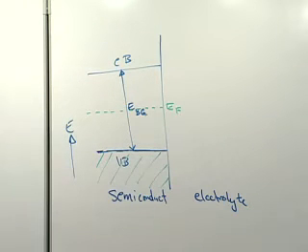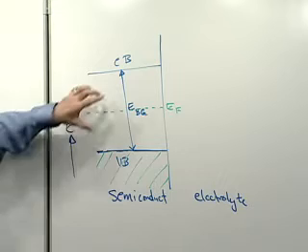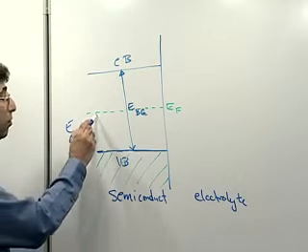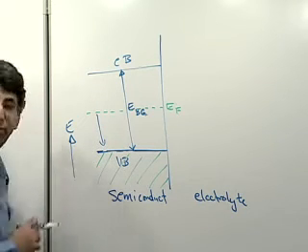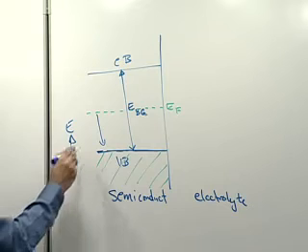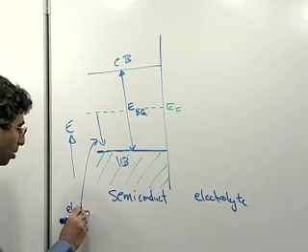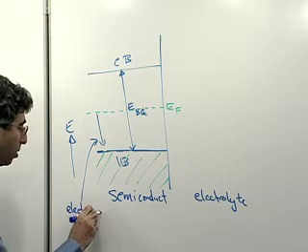We can dope semiconductors. In fact, not only can we dope them, but they tend to dope themselves if you're not very careful. If you add a material to this lattice that's going to withdraw some electrons from the lattice, that is more electronegative than the lattice, you move the Fermi level down. Okay? So we're adding something that's electron withdrawing.